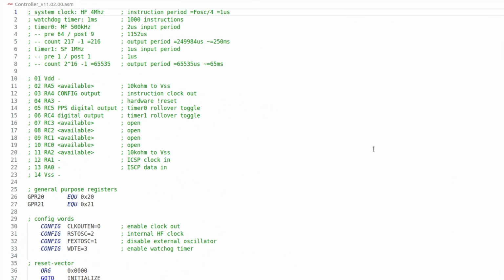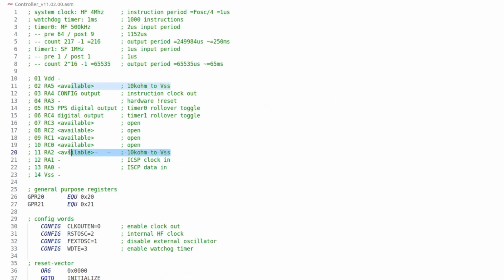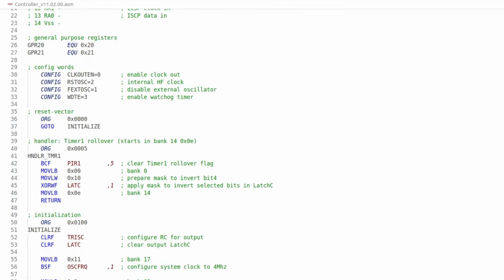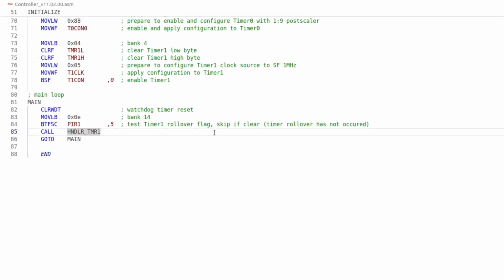We're going to start real simple and basically write some code that says whenever the button is pressed, the output LED will turn on. As we release the button, the output LED will turn off. And here's our code as we left it. Well, actually not quite as we left it. You'll notice I added a few comments to help me remember what's actually plugged into the microcontroller and which pin it's plugged into. So now that we've connected the button to pin 2, I'm going to change this line to reflect that. Then we'll move down to the main loop and add a few lines of code.